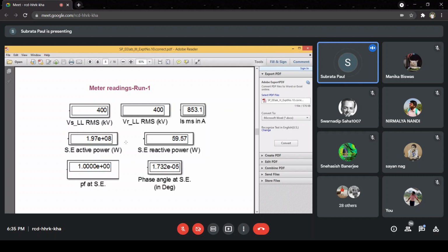And again, one thing you must notice: the surge impedance of a line is independent of its length. For a 400 kV line, surge impedance loading is frequently 550 megawatt to 600 megawatt. It is close to 600 megawatt. Sending end reactive power, per phase.